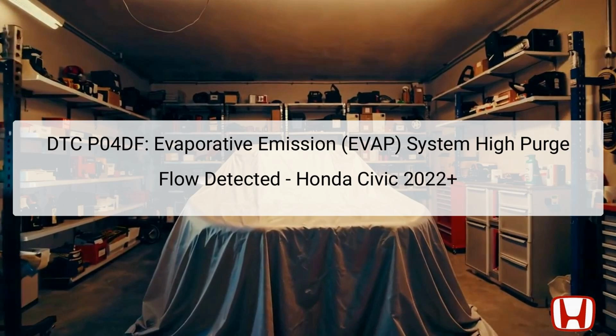The EVAP system is responsible for preventing fuel vapors from escaping into the atmosphere. It utilizes a series of valves, including the EVAP canister purge valve and the vent shut valve, which are instrumental in regulating the flow of vapors. When the vehicle is operational and the engine is stopped, fluctuations detected by the fuel tank pressure (FTP) sensor can indicate malfunction, prompting the Powertrain Control Module (PCM) to store this DTC for further analysis.